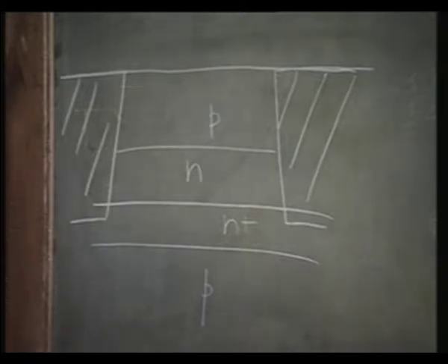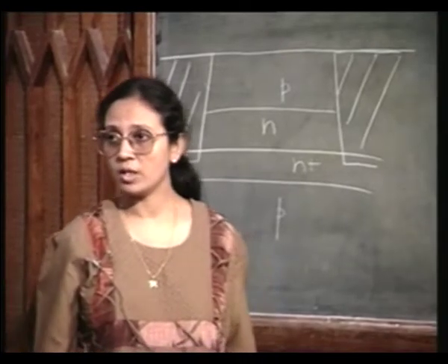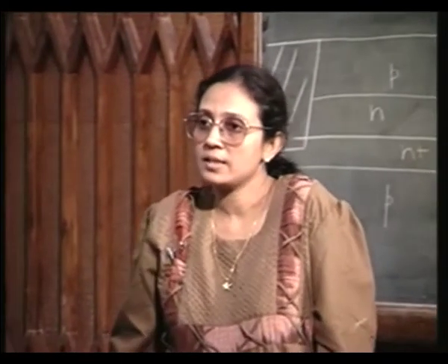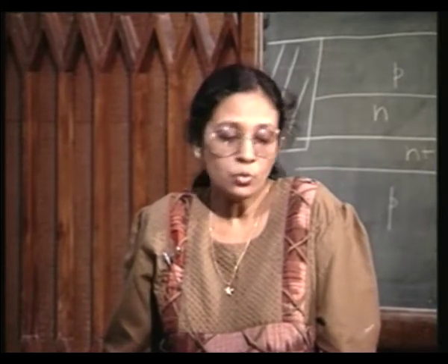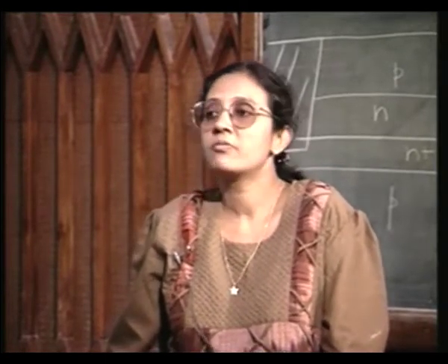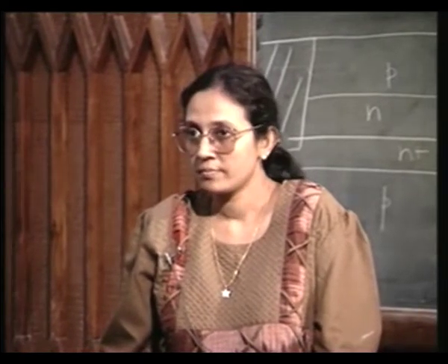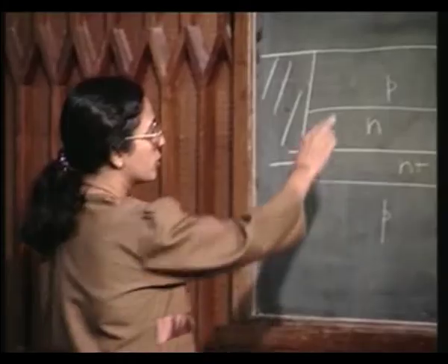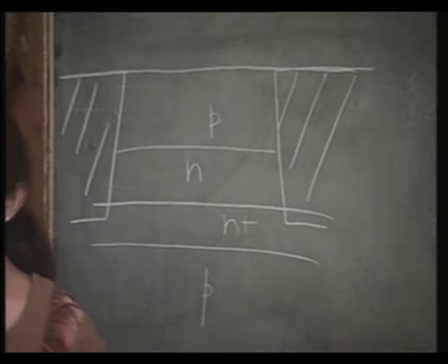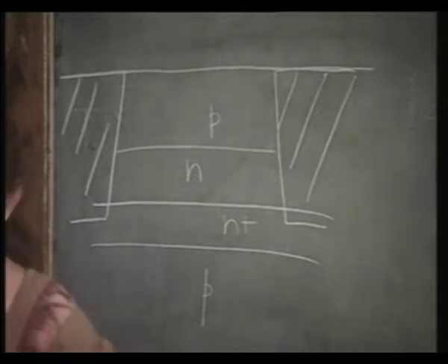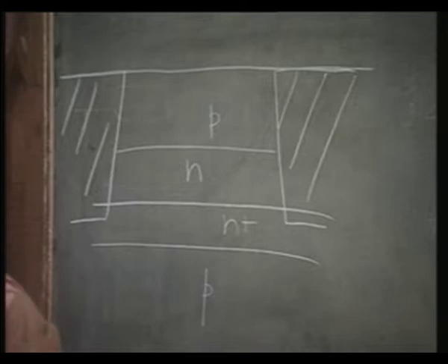Okay. So far so good, so far nothing has changed, so far my ECL transistor looks exactly the same as the conventional transistor we have already discussed. Now my first step is to define the extrinsic base. I have doped the intrinsic base. This doping is determined by the gain consideration, by the Gummel number. You have decided how much total charge to put in the base, fine. Now next step is how to obtain the extrinsic base and how to have it self aligned with the emitter.